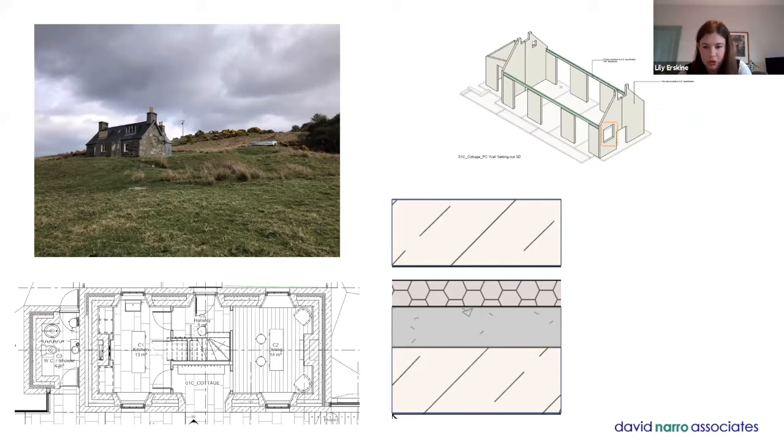I mean, there are tricks that we've had to use. It's not quite as simple as I make out. We've had to put in a precast concrete interior because a big thick stone wall is strong en masse, but as two thinner skins it doesn't work in the same way. So there's a bit of structural support in there. And I'll talk you through how we've dealt with precast later, because we've got a whole system for that.